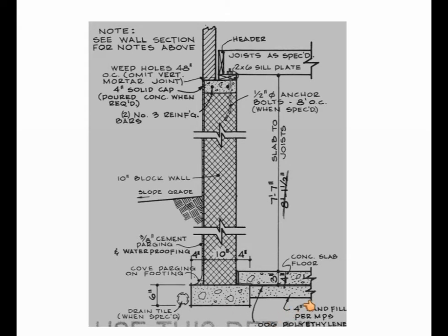If you look at the foundation detail drawing, you will notice that the bottom of the concrete slab floor is at the same level as the bottom of the foundation wall. Both of these are at the top of footing level that you created in the building information model. So the bottom of the concrete slab floor is at the same level as the bottom of the foundation wall.